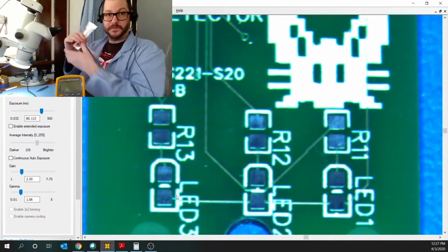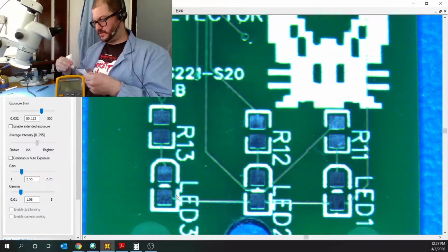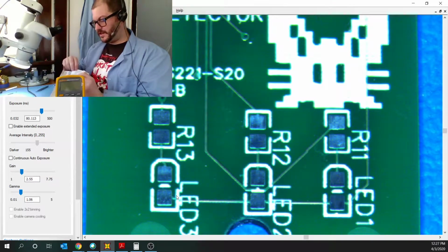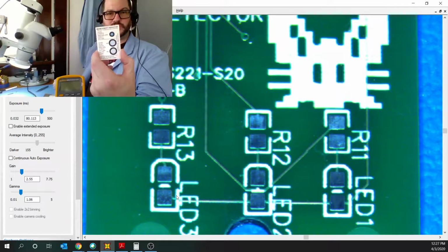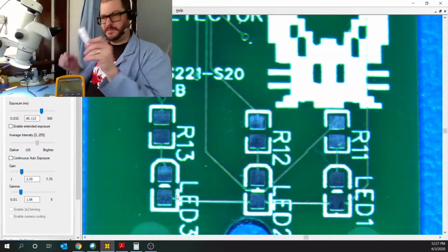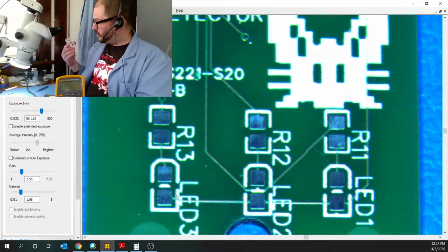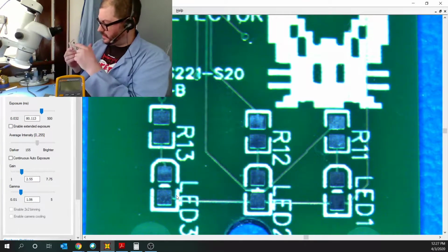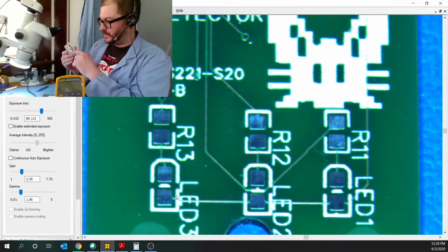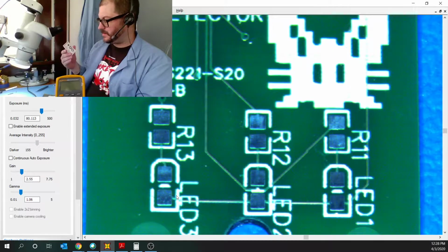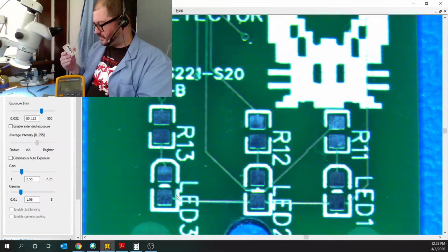So I'm going to open up the bag here, which tears open as such, and look inside. This actually comes with three things. It comes with a moisture indicator card. I'm basically looking to see if the parts are okay. It says level 2 parts, bake parts if the 60% is not blue; level 2A through 5A parts, bake parts if the 10% is not blue, and the 5% down here if this is pink.